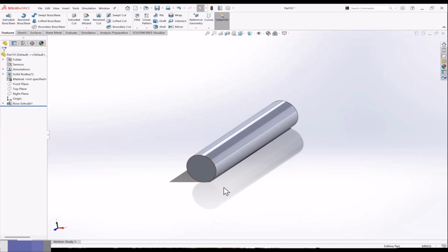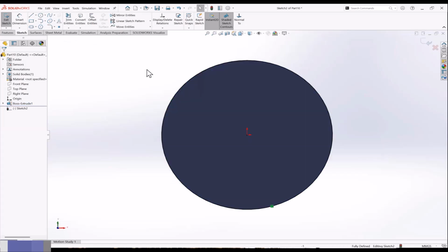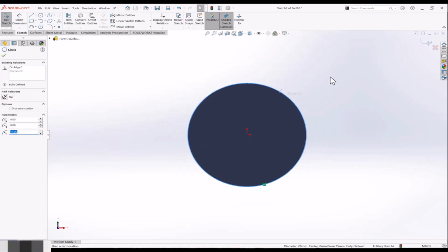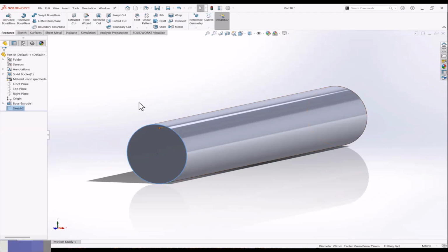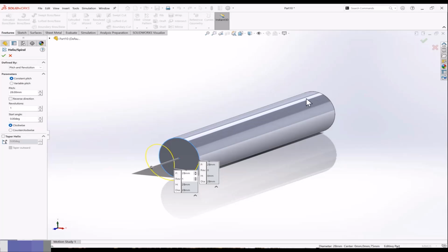So I want to place the curve. I just go to this face and use convert entities to convert the edges into a sketch. Get converted now. Exit. Now we'll use this. Actually, we need a helix here, so we'll use the helix command. To make my revolution over that, I'm going to use height and pitch. And we'll define height in the opposite direction.